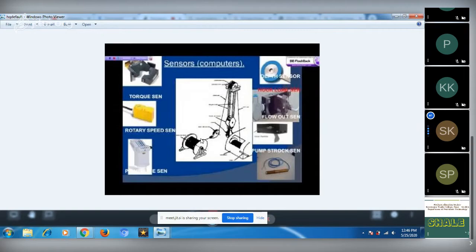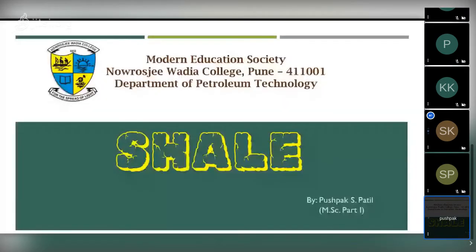So when we install everything, what will be the next point to do? Suppose our sensors are all in place, at the draw works, at the choke manifold, at the pit, and where we want to place the RPM sensor. What will be the next step? Obviously, the sensors will give you random values, right? So basically, we have to calibrate the sensors. The next step will be the calibration of all the sensors. Then after that, those sensors will read the correct value.